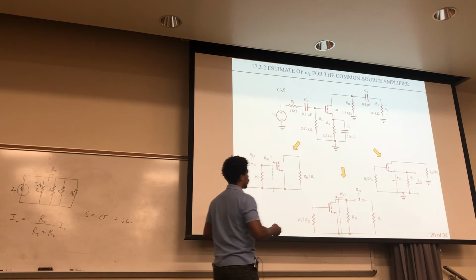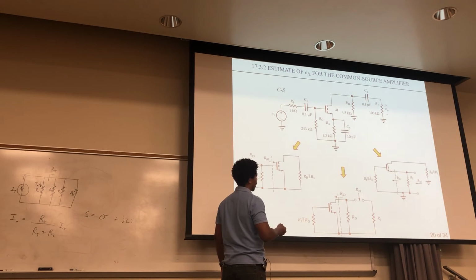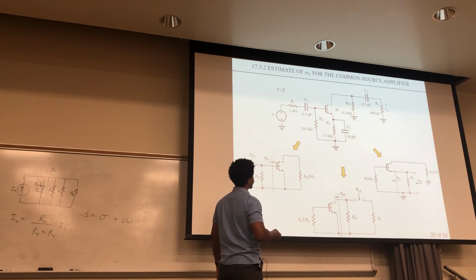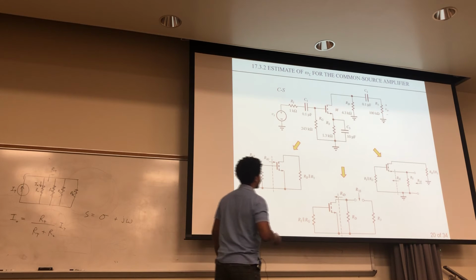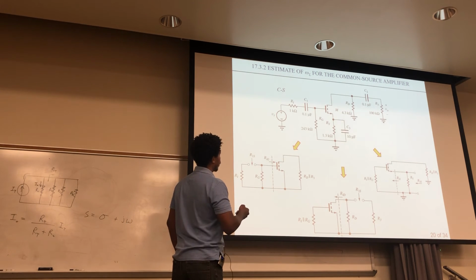For i equals 2, we'll get this, and so that capacitor C2 is replaced with R2S. These two become shorted. So that's shorted, and this is shorted right here. And then for i equals 3, this right here becomes the resistor we're looking at, and these other two are shorted.